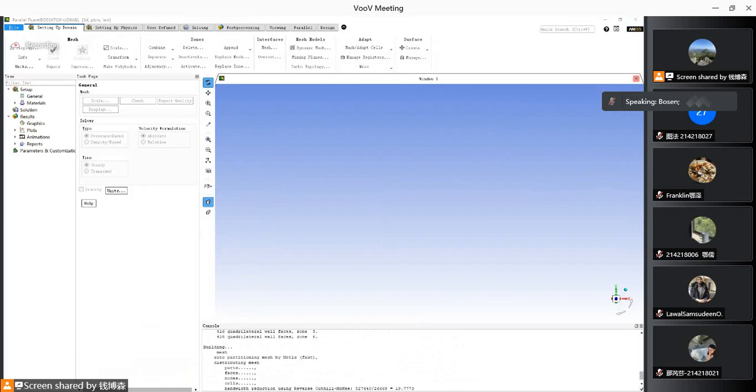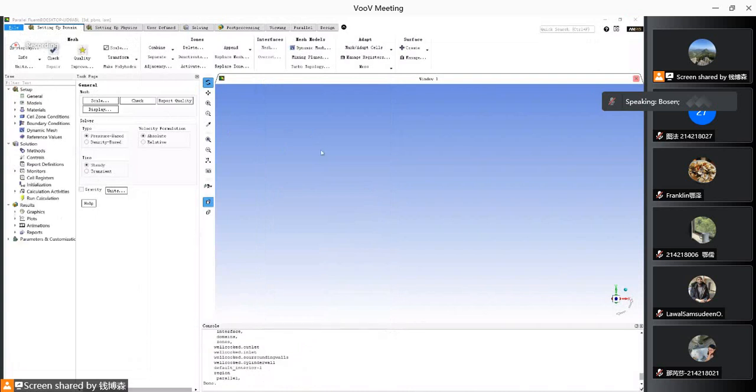Yeah, the Star CCM file collapsed again, and I think that's mainly because the element size I set is too small. It's beyond the capability of this computer. It just ran out of memory. So I will try some larger number. Maybe we can switch back. Please excuse me for a sec. Volumetric control.